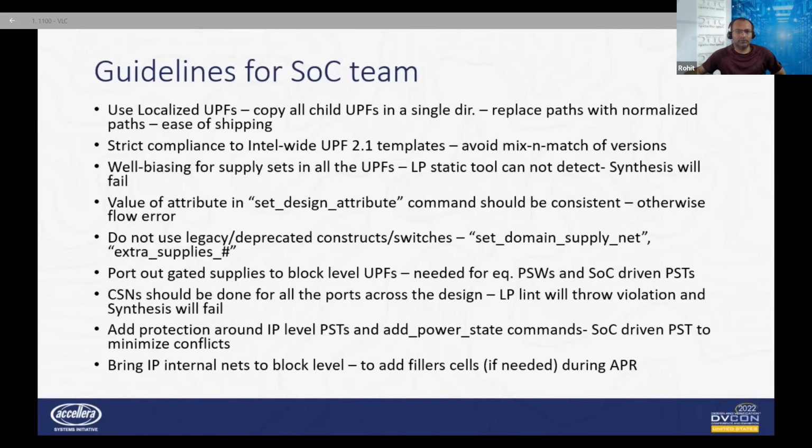Usage of deprecated and legacy UPF constructs can cause errors during synthesis. Some of the constructs like set domain supply net and extra supplies cannot be used along with UPF 2.1. Again, the LP static check tool may not fail, but during synthesis, the tool will definitely error out.